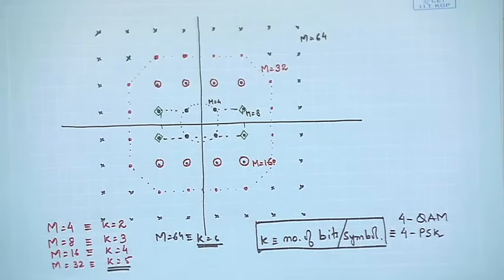Now, if you go for QAM signaling, you are efficiently using your signals, because you have complex signal transmission. If it is PAM, then it is double sideband, and you need to resort to single sideband transmission in order to achieve a certain spectral efficiency. If you are doing QAM, you would achieve the same spectral efficiency as you would with a single sideband system. So, now there are 2 important aspects that we need to look at.